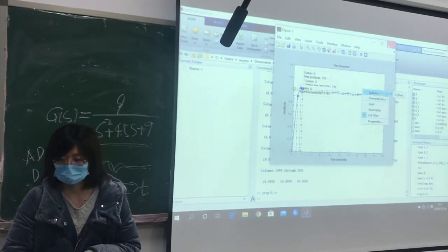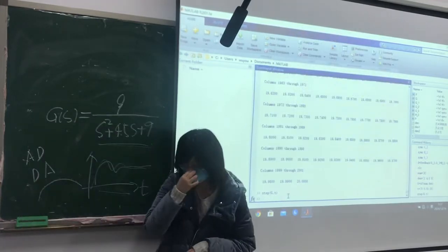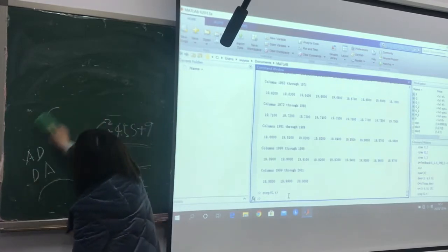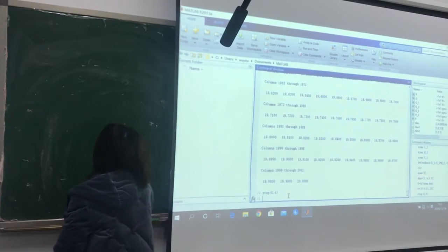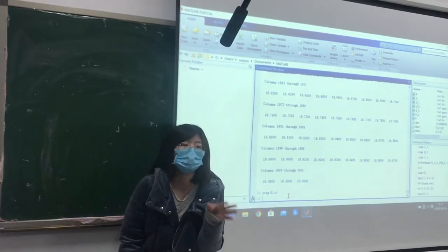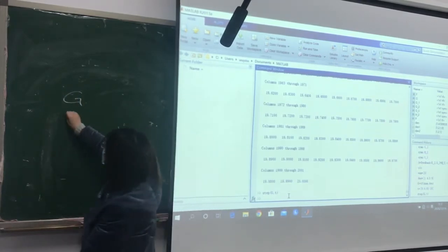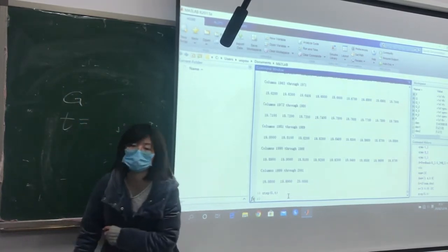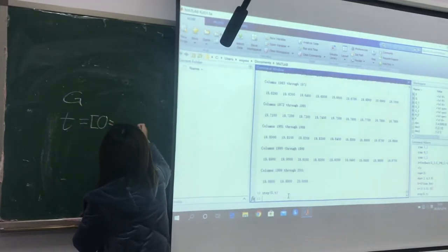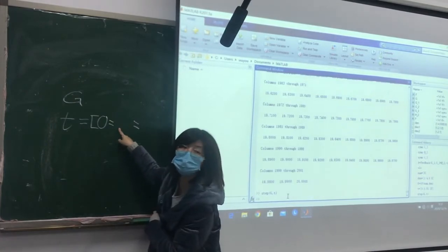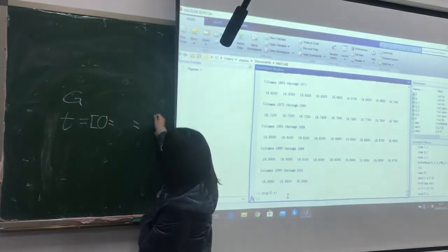This is the way. First define the transfer function. Then you define the time t-axis by this code, from 0, with the sample time you choose, and ending at whatever second you choose.